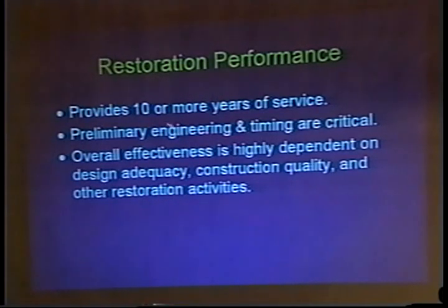You need to do your preliminary engineering early if you're going to do that, because you want to get ahead of the curve, before the distress has reached those critical values. And of course, the overall effectiveness of your restoration method depends on your construction quality, other restoration activities you may have, the condition of the pavement, and such.